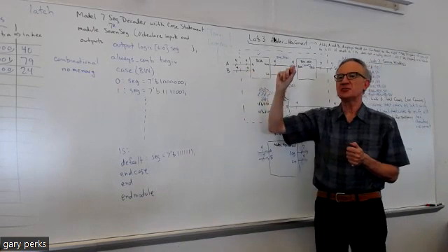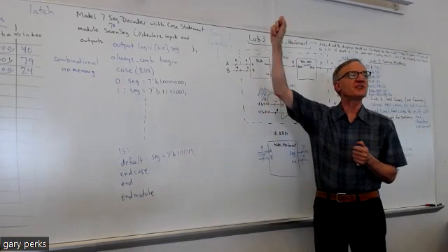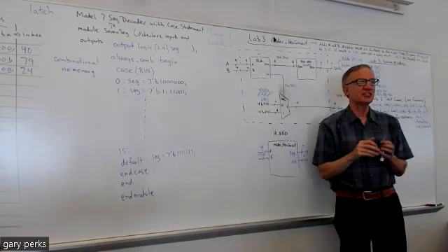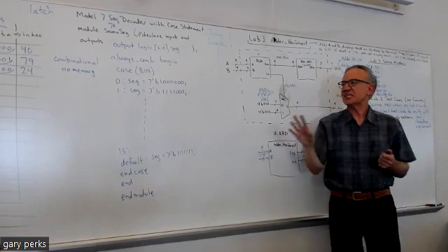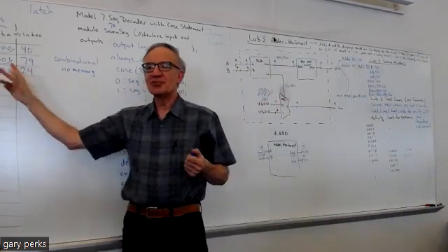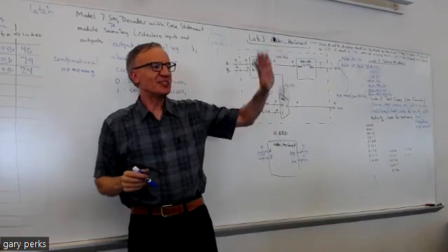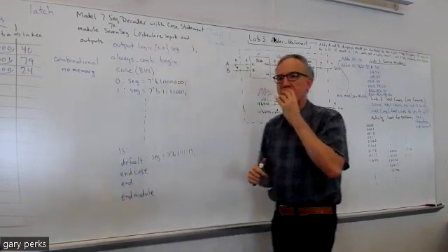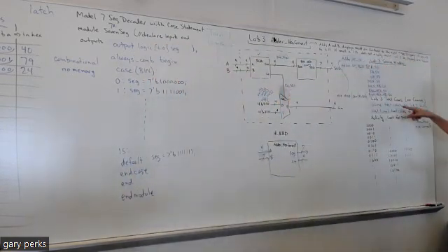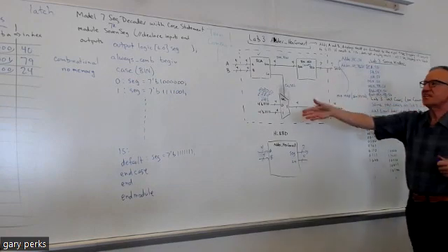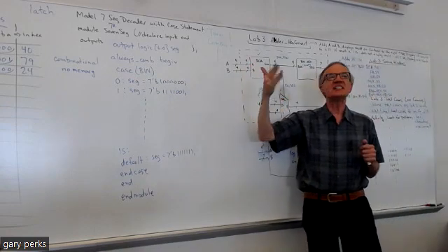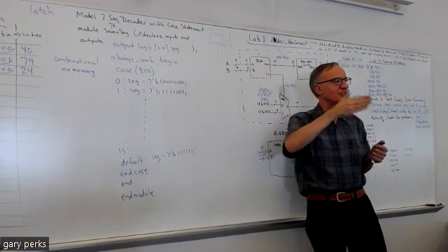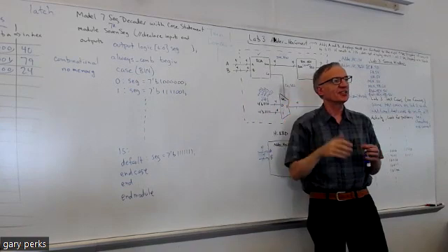And with the other input, just go 0, 1, 2, 3, 4, 5, 6, 7, all the way to 15, just to make sure that all the hex characters are appearing as they should. Because sometimes it's very easy to reverse a 1 and 0, and then when you look at what's being displayed, there's a segment that's not right, and that happens quite a bit. So if you do the test cases that I just suggested, that would be 26 test cases, right? It would be 10 from lab 2, and then another 16 just to make sure all 16 characters are appearing.